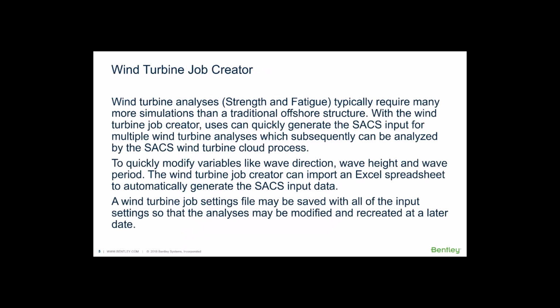So I'm just going to briefly talk about what the wind turbine job creator is and what it's intended for. When you run a wind turbine analysis, either a strength or a fatigue analysis, we usually require many more simulations than a traditional offshore structure analysis requires. And so the wind turbine job creator is intended to quickly generate these analyses based upon some preliminary data that you create, and then using the Excel spreadsheet information, you can use a lot of different variables that can modify what that initial data is. I'm going to show some examples later on, so if this is sounding a bit vague, we'll look at it a little bit more closely. But that's the basic idea behind the wind turbine job creator.